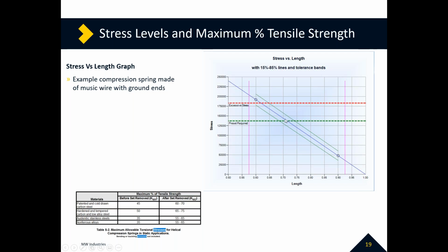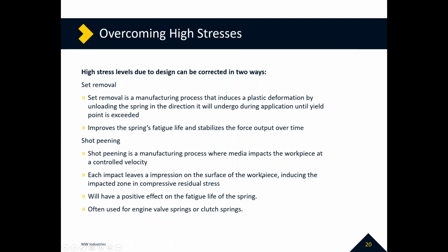But what we're trying to make you understand is the ideal thing, again, we're just talking about carbon steels right now, is when you run your stresses, we try to maintain them as low as possible. We know we can't always get there, but getting as low as possible will give you the best economical price, because we won't have to do any post processing.